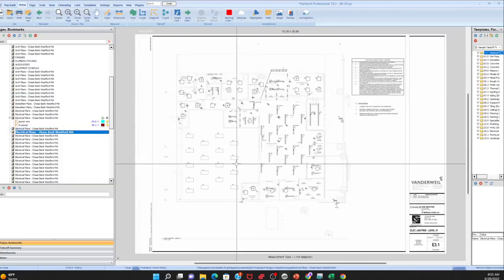Yes. For what you said, conduit by 3. So, right. You have 1,000 feet of conduit. You have 3,000 feet of wire. So, for instance, let's just say it's the home runs, right? If you measure like we did, 1,000 feet of home run, you've really got 3,000 feet of number 12 inside that 1,000 feet of conduit, right? Because it's multiplied by 3. So you want to separate the conduit run from the wire run, right?